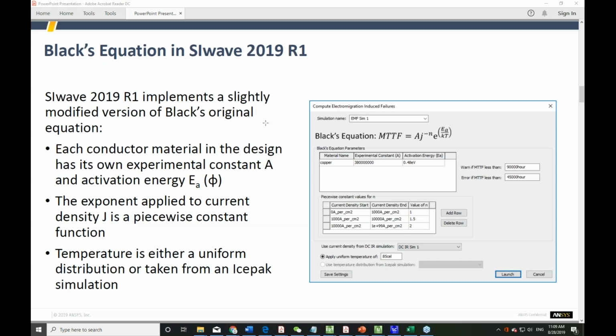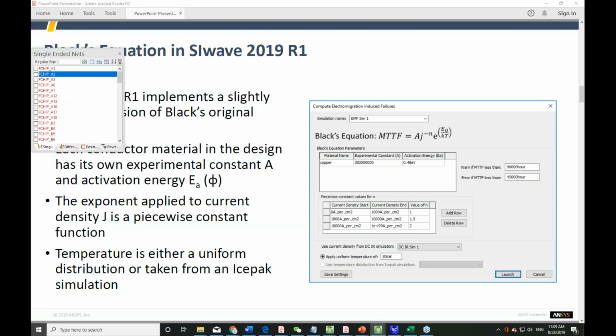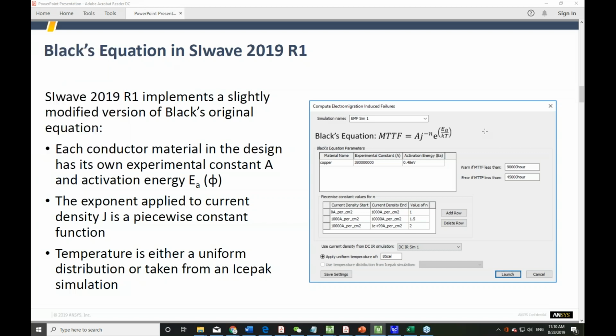That's a 2.5D hybrid solver that can quickly give you analysis on chips, packages, and PCBs on different physics, such as DCIR drop, extracting S-parameters, generating near and far field, an impedance scan, and time domain crosstalk as well as regular crosstalk.